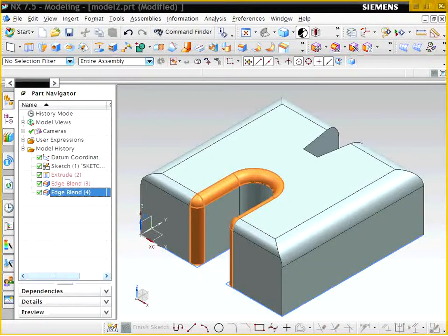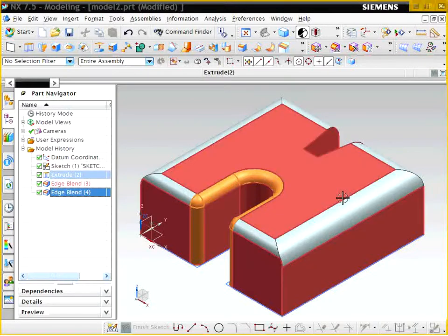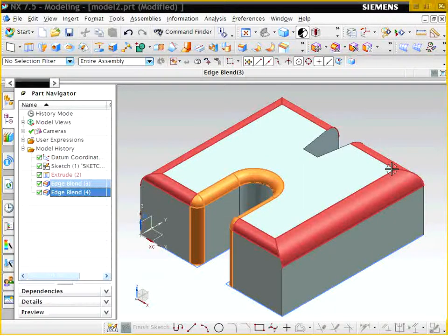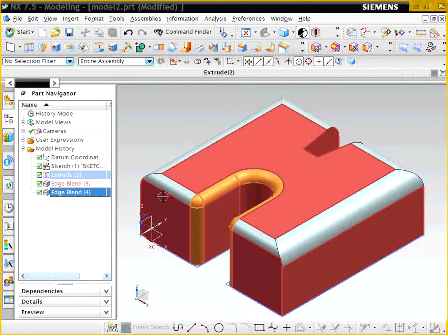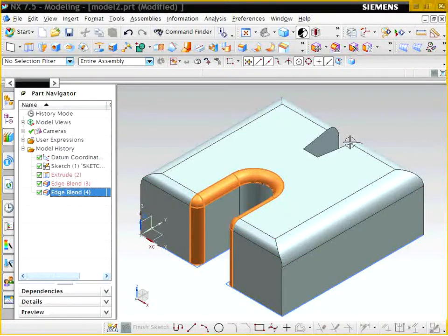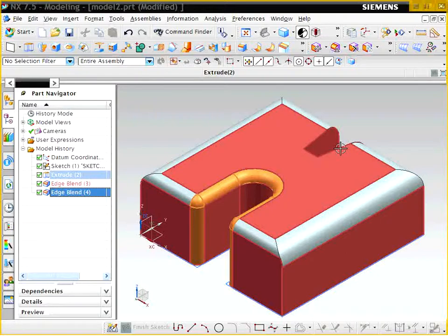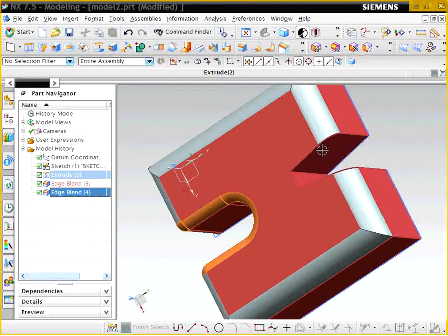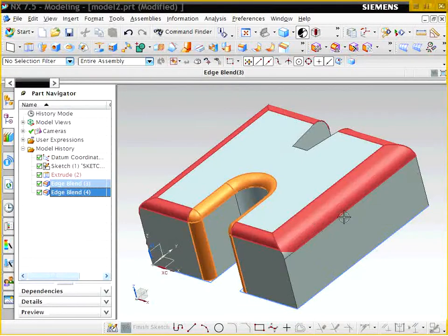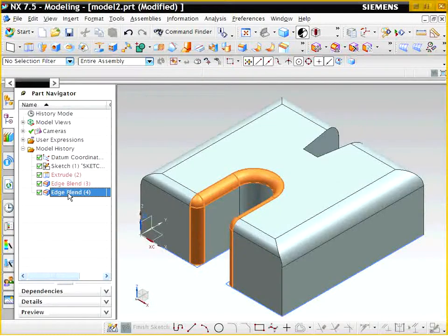So let's continue chapter 7. What I'm trying to show you here is I'm working with the same part I had before, and last time what we did was we used different radius edges around this part, and we also smoothed this inner surface. So in this lecture, what I want to do is smooth this other side to be a rounded edge, and I also want to create an edge here that is varying in radius as we go along one edge, not along several other ones.